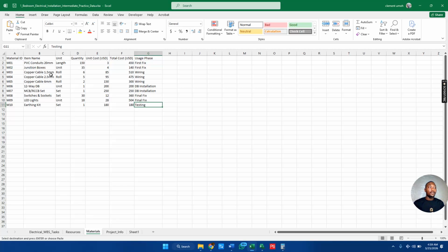Over here, that's 3 red, 3 black, which gives us 6. Then we have 2.5 cable, which is black, red, and green: 2.5 black, 2.5 red, 2.5 green, which means 2, 2, 1. Green is 1. Okay, so let us do this one. We also have our 6 cable. This is basically used to draw supply into the house. It can be single core, yeah, single core 6 cable.